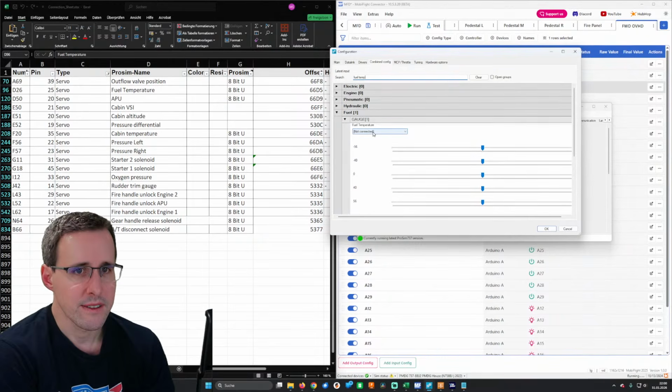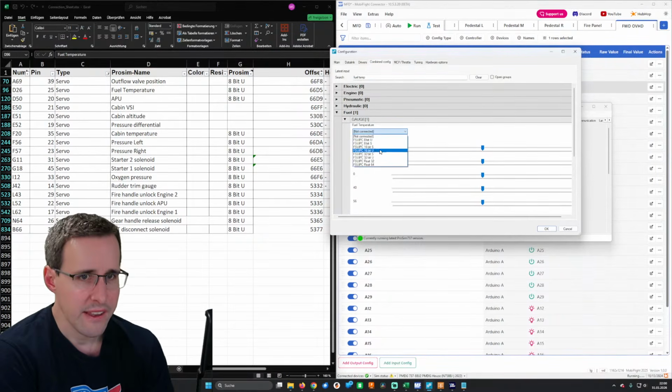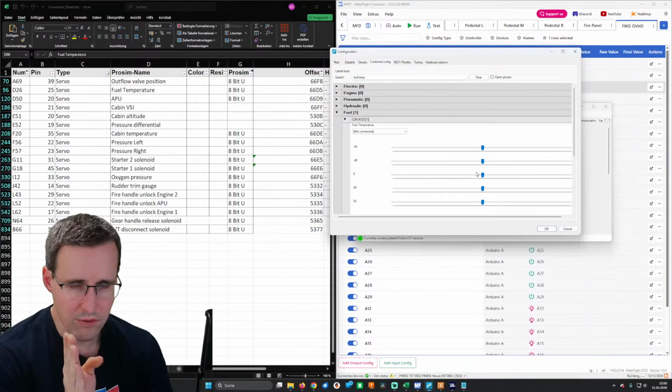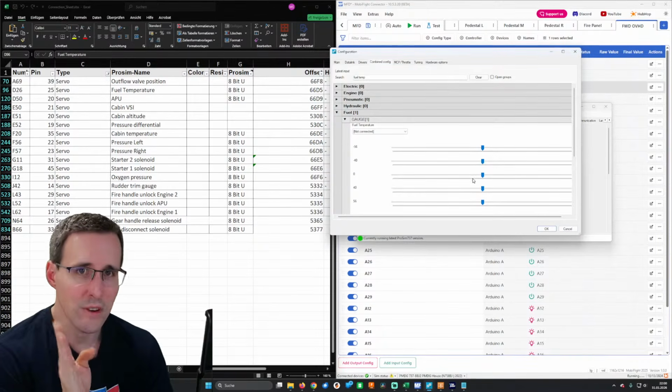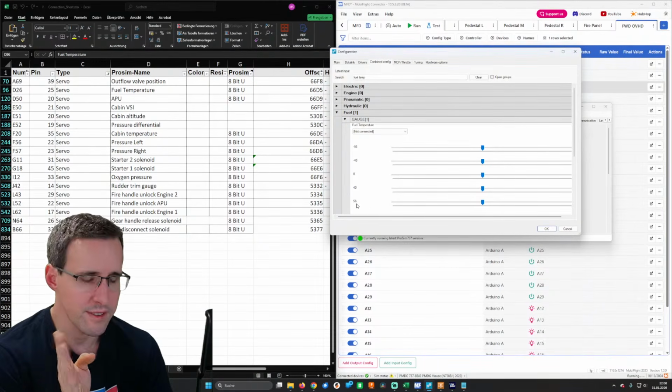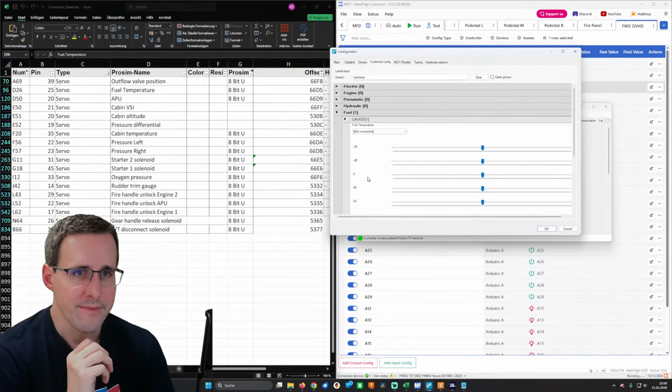At the moment, I had inserted here an FSUIPC offset and then controlled with the sliders here that the servo motor comes into this position, controlling the needle, so that the needle is always at these key positions, I would call it. 0, -40, -56, and the same +40, +56.